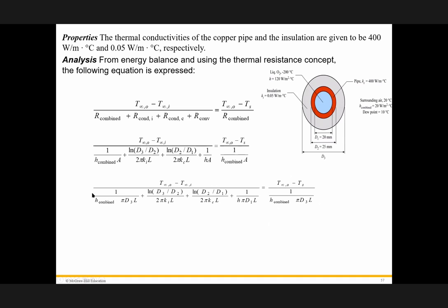Since we know all the information, if we substitute here, what is the unknown in this equation? D3, excellent. The only unknown is D3 because we know the surface temperature, because we mentioned it should not be below 10. If you substitute, your equation becomes like this. Again, this is just rewriting the equation. This is this one, this is this one, right here, and with all the equation, you can calculate D3 from this part. And then, okay, write it down.